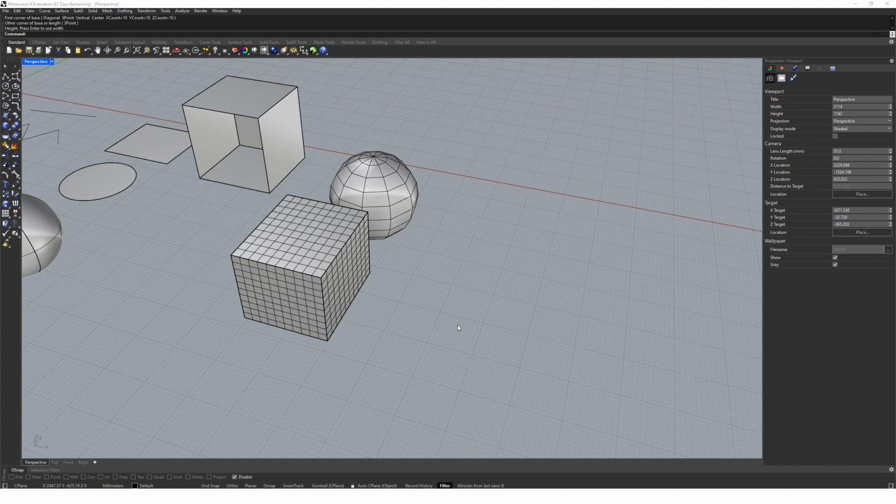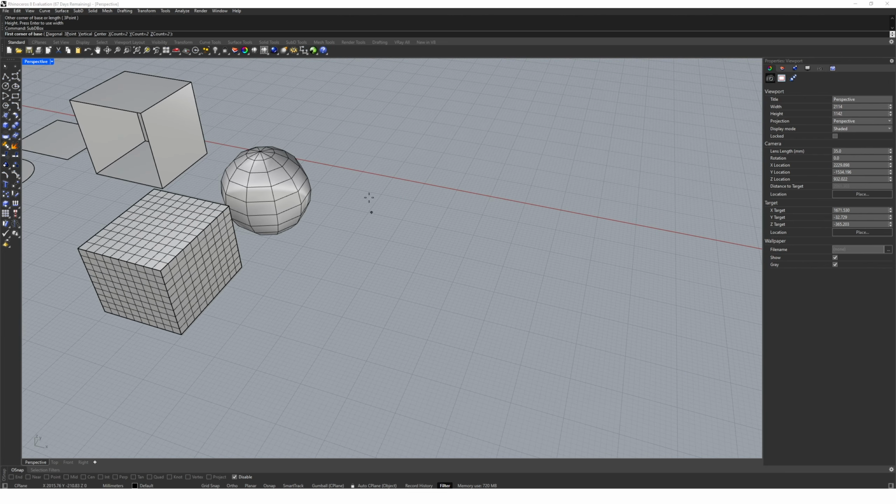Another newer geometry type inside of Rhino that was added in Rhino 7 is something called SubD. SubD is a spline-based polygonal geometry type that allows for the creation of accurate, continuous geometries. It's a great tool for freeform modeling and sketching, and we've got an entire course on the different designs available if you want to learn more. Let's create a SubD box, so let's type in SubD box into the command line, and it's going to be the same process as our other creations.